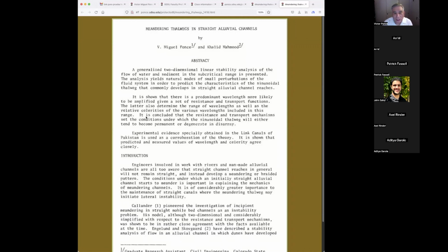So we did this research with Khalid Mahmoud. Like I told you earlier, I'm not going to specifically talk too much about it, but I want you to get the gist of what we did. What did we do? We did a generalized 2-dimensional linear stability analysis of the flow of water and sediment in the subcritical range is presented, meaning we were going to do some dynamics here, perturbation, modes of small perturbations.